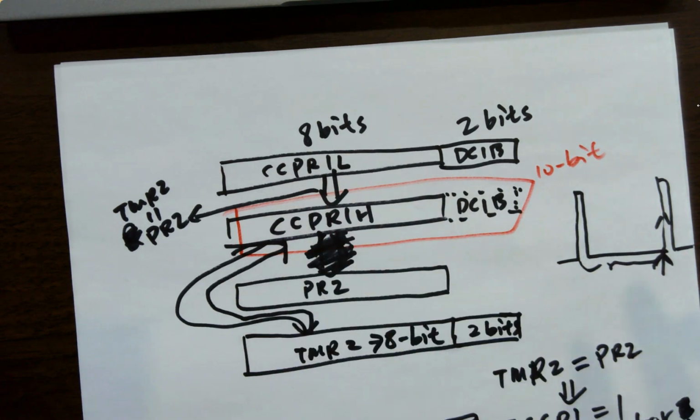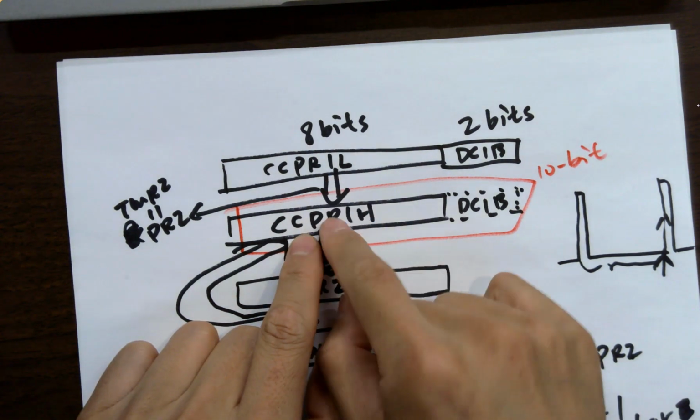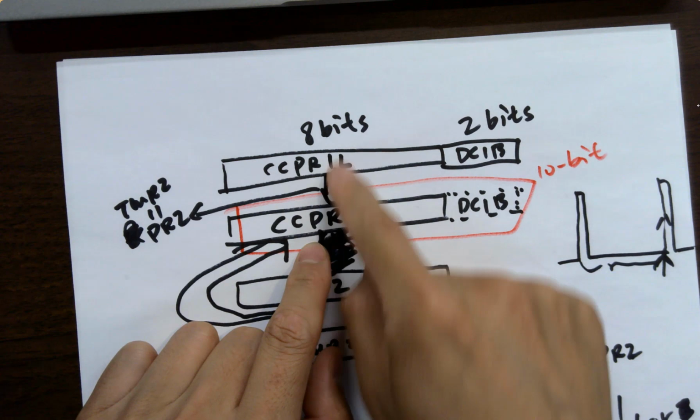I usually have all the registers working with the other parts of the digital block before a latch. So whenever it's all ready, you send the one clock and send it out. So it's not interfering with whatever is in here. Usually that's the way to do it, and I think it's probably serving the same goal here.